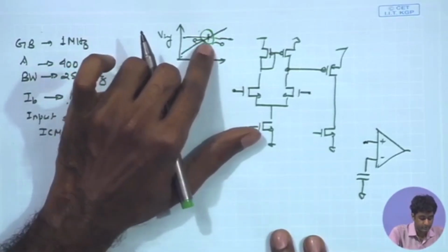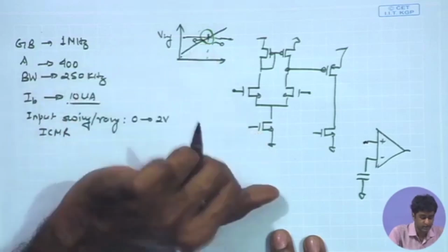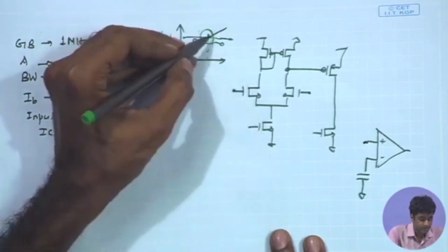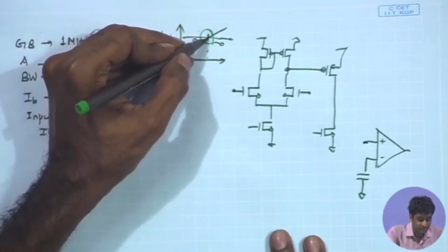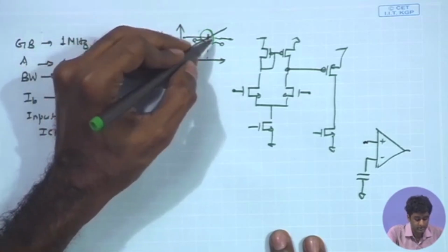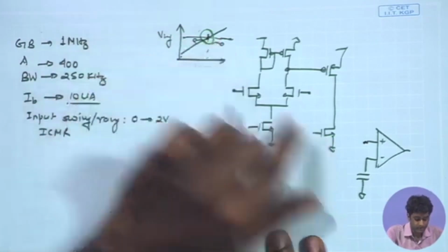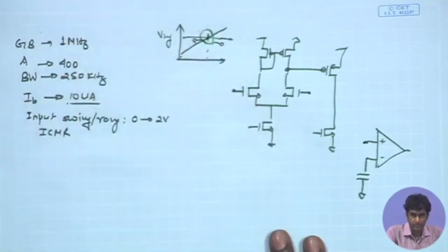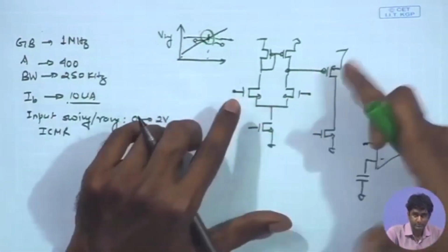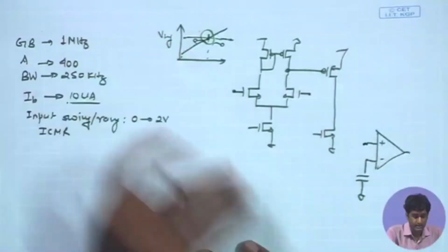So, if the response of the comparator is fast enough and the gain is sufficiently large, whenever the ramping signal crosses the reference or the stored sampled signal by a small amount delta V, it will be able to switch, provided delta V times A is equal to the full swing as we have designed earlier.